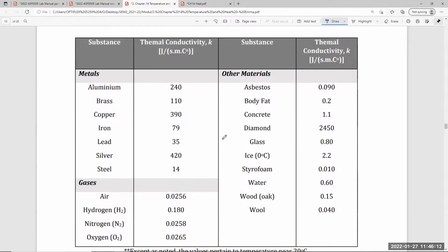As mentioned just now, metal has a high coefficient of expansion, as we understood last time. But you can see here that metal also has high thermal conductivity compared to non-metal, which is very low. Metal has a high K value. This is the K value. The unit is also in Celsius, so don't worry about delta T; you can use Celsius.